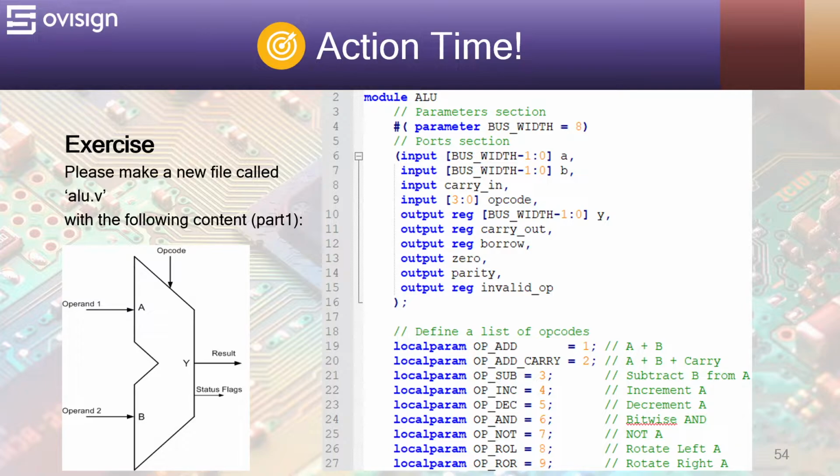If we look at the output ports, we already know how the code is going to look. The ones declared as output reg are going to be used in the left-hand side of always blocks, and the ones declared as outputs are going to be used in continuous assignments.